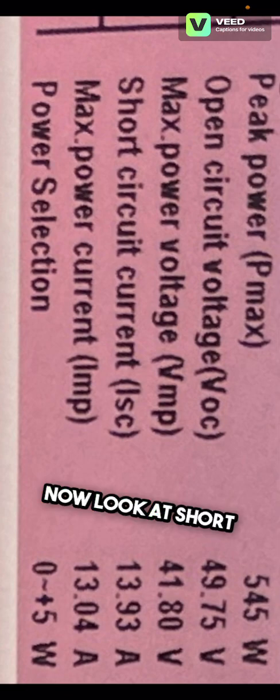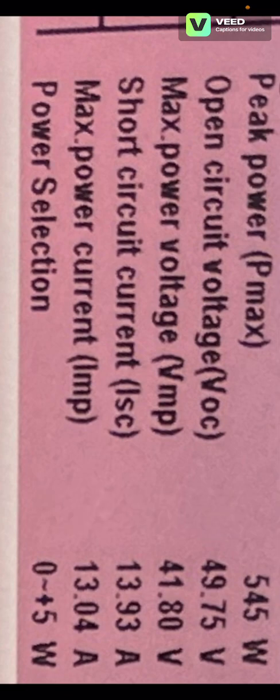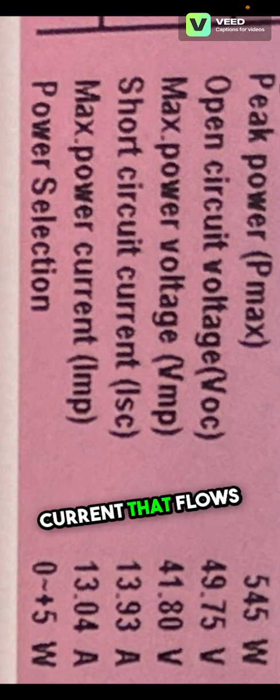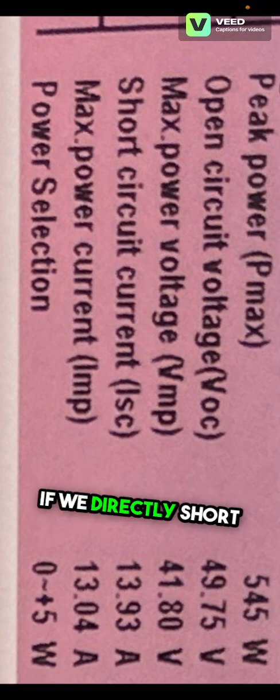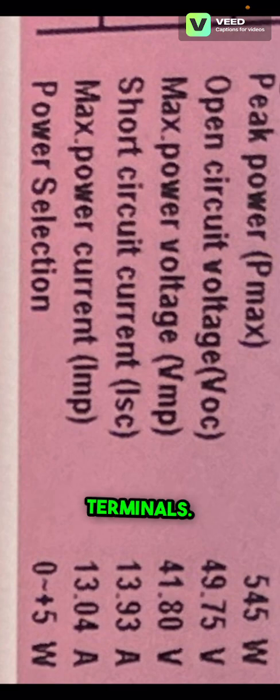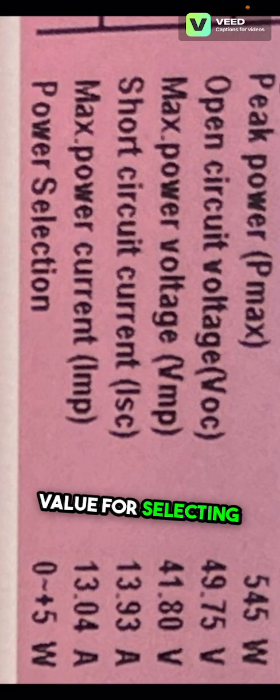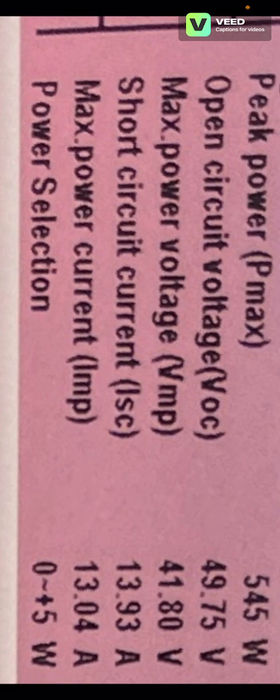Now look at short circuit current, which is about 13.93 amps. This is the maximum current that flows if we directly short the panel's terminals. We mainly use this value for selecting DC cables, MCBs and fuses.